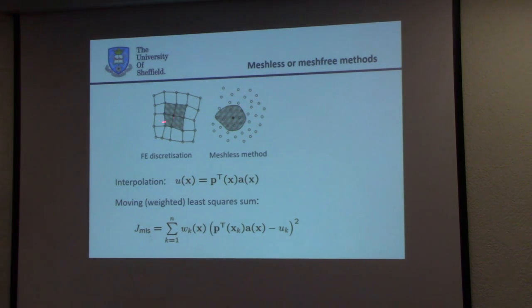So this is called mathematically the support of this node. The gray area is the support of the node, the area where shape functions are non-zero. Now in the finite element method, this support is directly one-to-one tied to the elements that surround a node. You can decouple that.